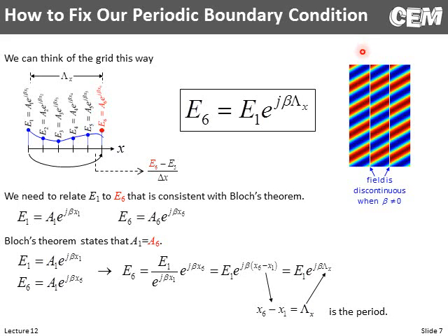So if we're using periodic boundary conditions, let's take the field in some unit cell. If it is periodic, I should be able to stack it onto itself and see nice continuous fields, and I don't. That's because our wave is coming in at an angle and we have these phase discontinuities. So this tells us we can't immediately apply the same boundary condition we talked about in the last slide, because the fields on the left side of an interface do not equal the fields on the right side of the interface. And why don't they? It's because of this phase term.